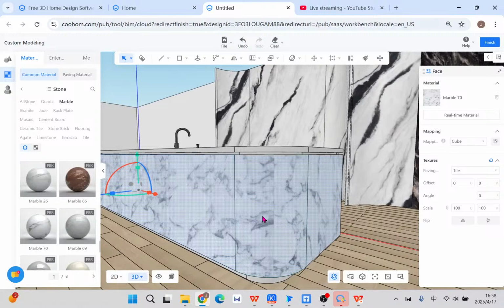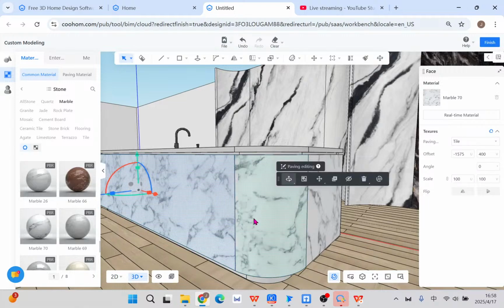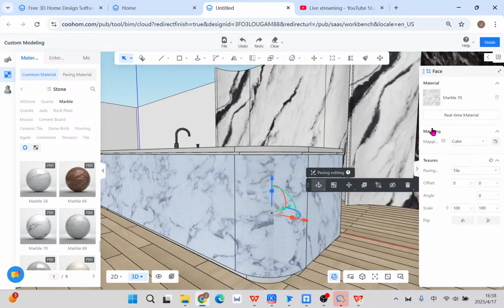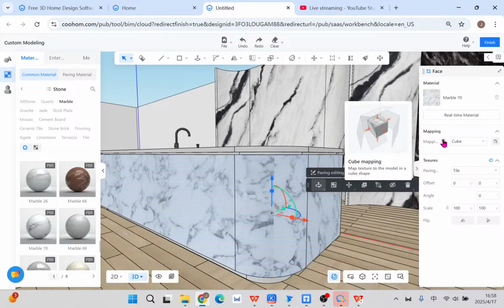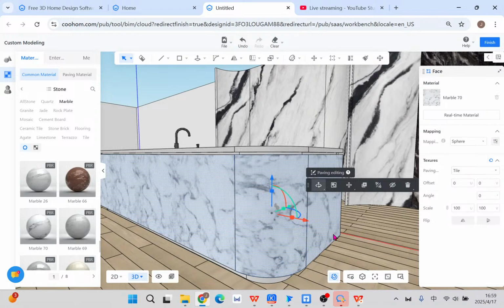Most of our users may think, okay, I just give up. I just need to disconnect and then make it changing. But just pay attention, even if you disconnect that, if you want them to continue, it's really hard, right? So undo it. Here I show you, just changing the mapping is fine. For the mapping, the default setting is cube, which definitely will find one border between this curved surface. So what you need to do is changing them into the sphere.